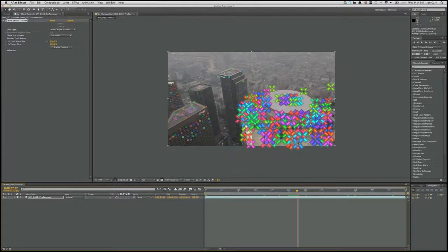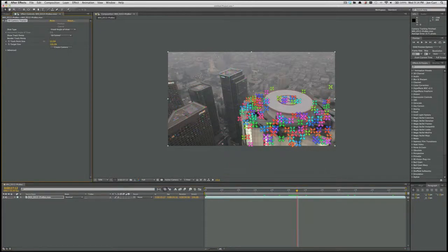You can also adjust the size by coming over here and pulling them down, bringing them up if you want them to be bigger, which is nice. So let's dig into some of the settings. I'm going to scroll down the Advanced tab, and what you can see here, this is the most important thing, the average error. Now this is 0.71, and that's really good for a scene. The average error represents the average distance between the 3D solve points and the 2D track points.